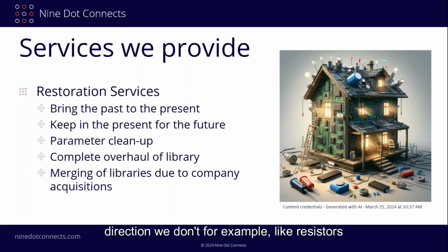We don't, for example, like resistors, they may want to make them more generic as opposed to calling out each and every single 0402 brand out there, for example. And then, of course, the merging of libraries due to company acquisitions. This happens quite often. And a lot of times it's really interesting to see what the two companies' libraries look like. So for example, we had one customer, everything was in integrated libraries, another one was on Altium 365. So they wanted to merge their libraries together. So we had to basically take everything together and make that come together in Altium 365.